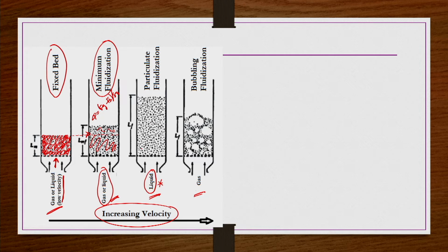And then you can see here that at any location in the bed, you take the density of the bed, it is the same actually. That means at any location within the bed, if you try to calculate the volume fraction of the solids and the volume fraction of the liquid, it is not going to change much from one location to another location. That is the reason this fluidization is so smooth.